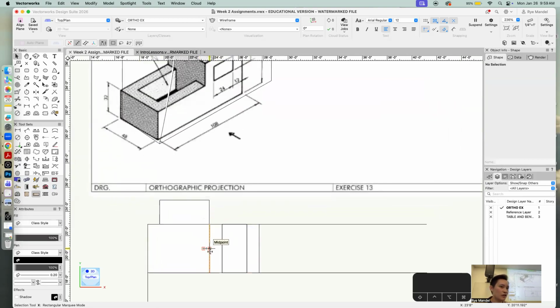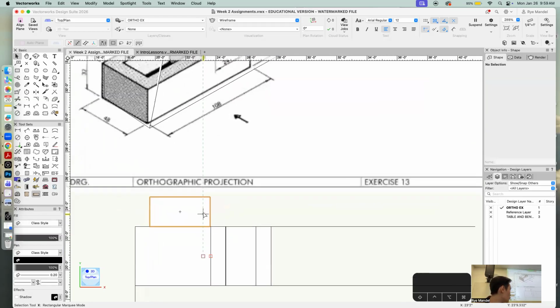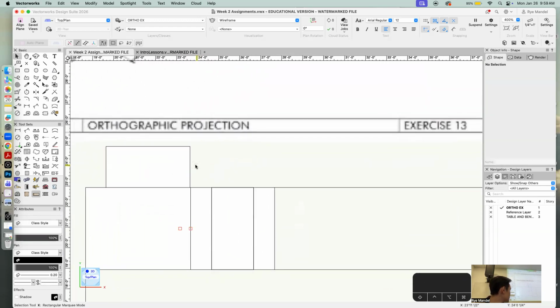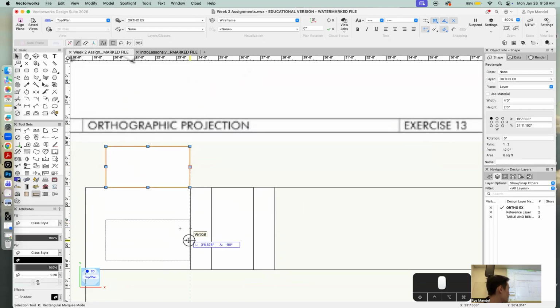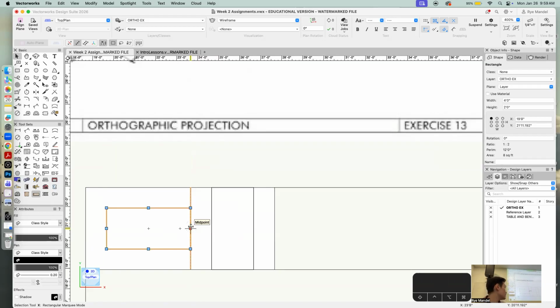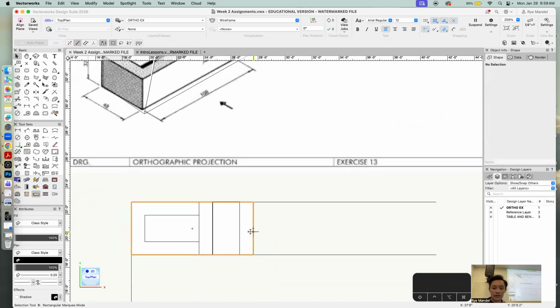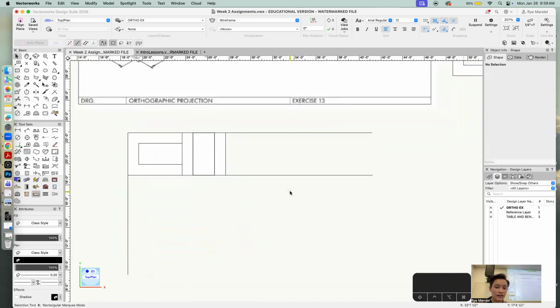If you have your snapping on, which we all just redid, you can take it from the middle and hover over it. Your little red snapping points will appear, and then you can move it to your midpoint and it'll snap automatically. I'm not hitting shift. You can tap or hover automatically and then bring it over to that middle point. And that's how I did that. Okay, any more before I move on to doing another view?